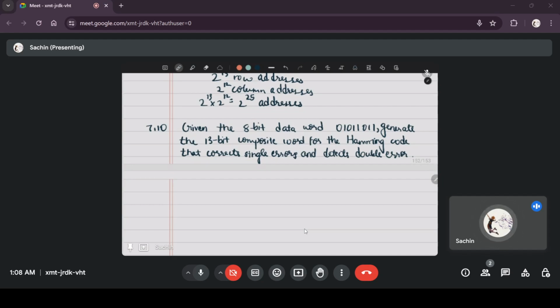So the (12,8) Hamming code itself is this. You have parity 1, parity 2, and the third bit of the code, which is the first bit in the message, then parity 4 followed by 3 more bits, parity 8 followed by the last 4 bits.